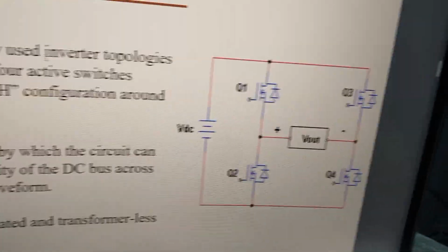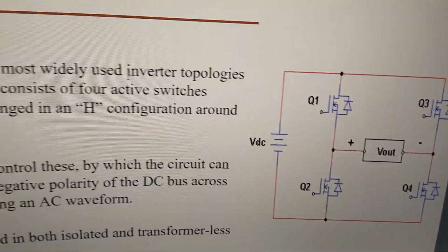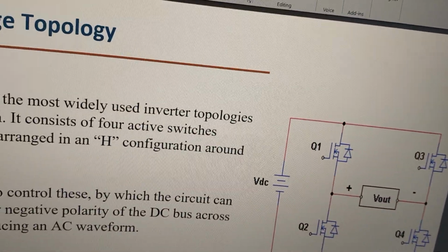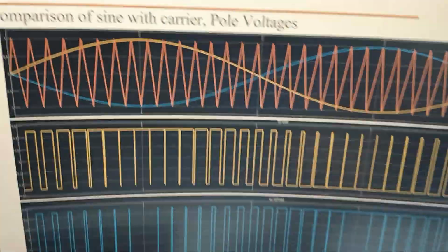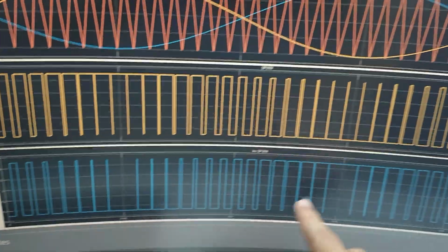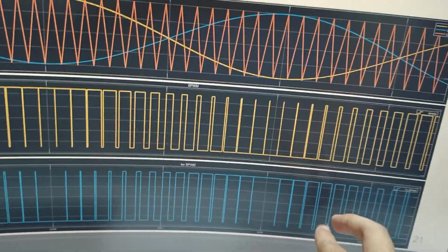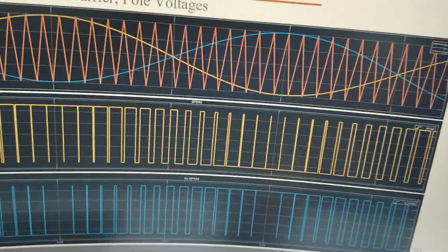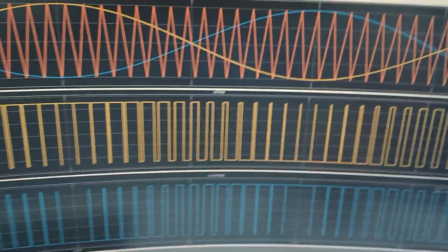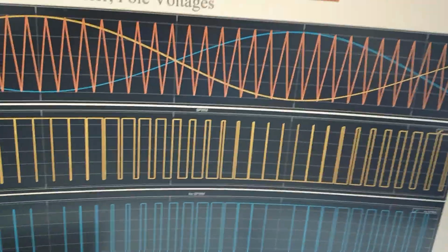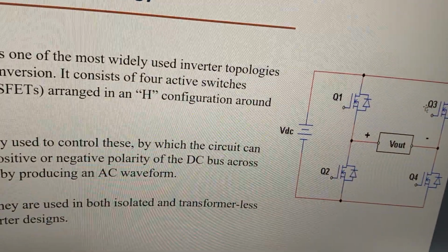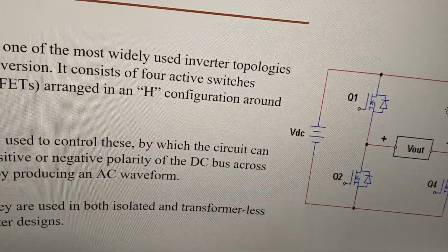So of course you get better waveform quality, and also filtering becomes easier, because, as you know, the output of your inverter, if I just show you the image, is going to be between plus VDC and minus VDC. It's going to roughly look like this in the case of unipolar, and I'll show it to you in hardware later. But basically, filtering unipolar is easier, because if you view the voltage across your load, it's going to be at double your carrier frequency.